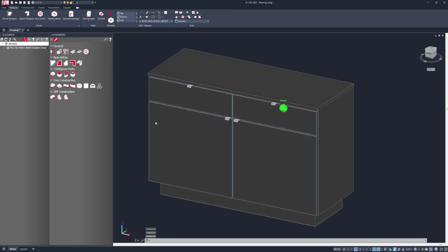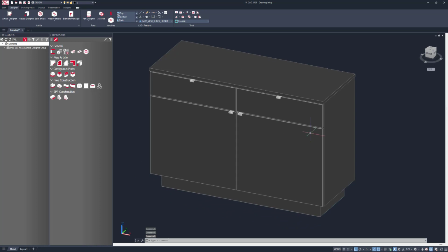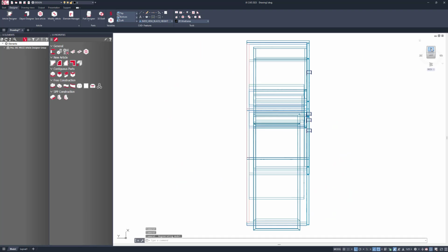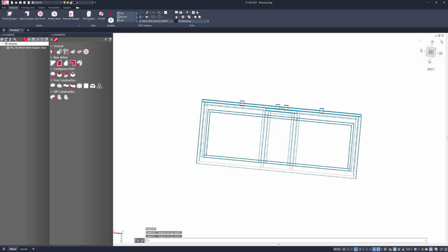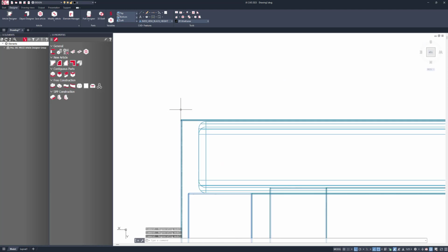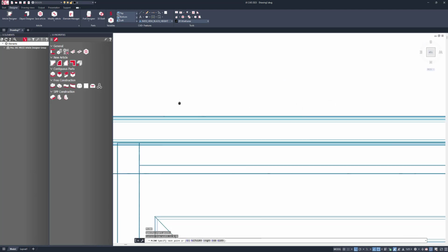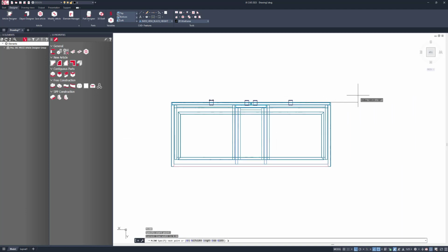Okay, so the next thing that I want to do is maybe make some minor alterations, and then we'll put this into production. So I'm going to go back up into wireframe mode, go into my top view, and in here I'm going to just start a polyline command, which is going to go this way with an arc and a radius of, I don't know, 4 meters, let's say.